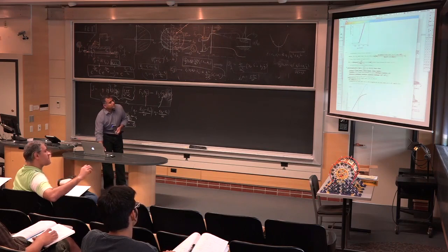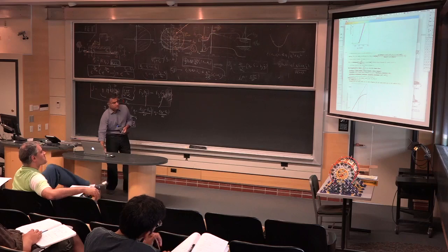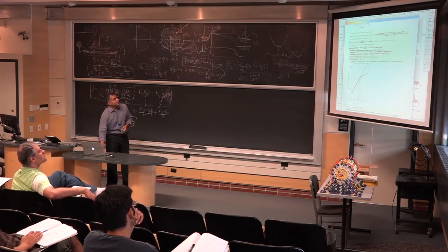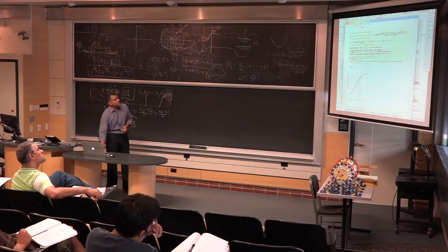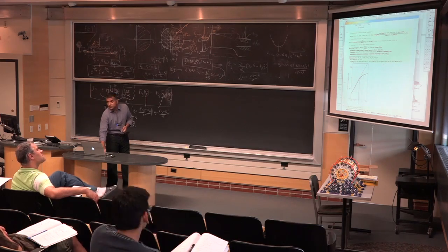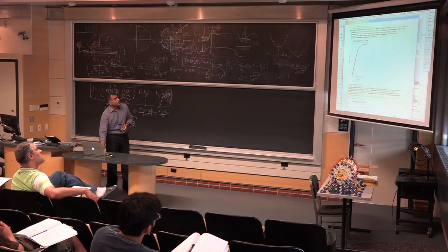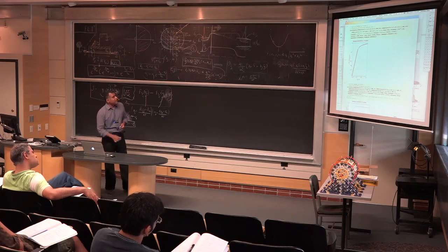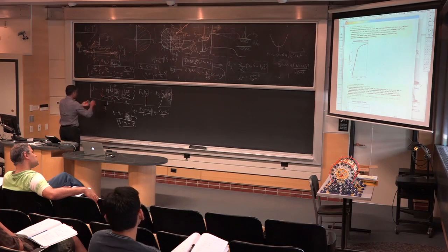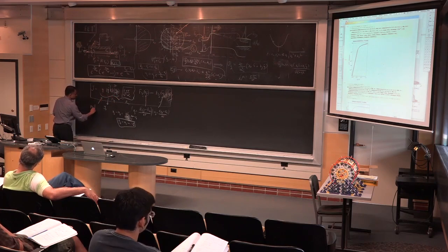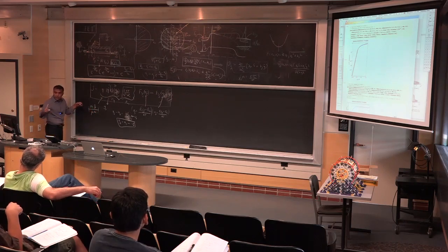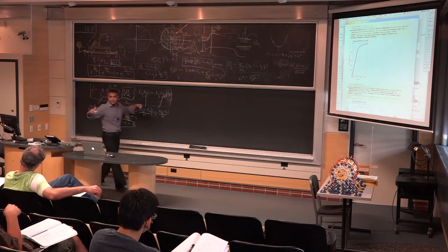And then I define my Fermi-Dirac integral of half order. You see, this is something we did today, square root of something over 1 plus exponential. Define all that stuff. And then write down your ballistic current is whatever this J naught coefficient times Fermi of the source minus Fermi integral of the drain. Right? And here's the current. So drain current as a function of gate voltage, drain current in milliamp per micron. Those are the units. So you can check the units here. The units preferred in semiconductor FETs is milliamp per micrometer. How many milliamp per micron width of the device? If you have a wider device, it's more current. Right?